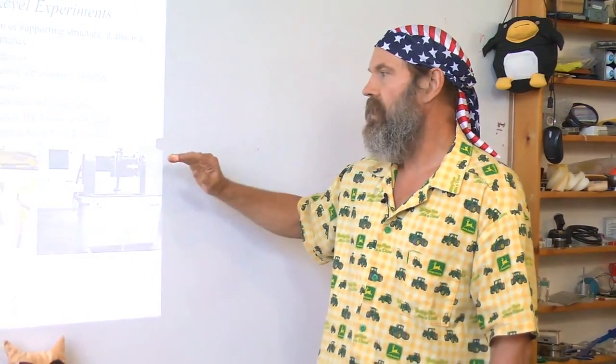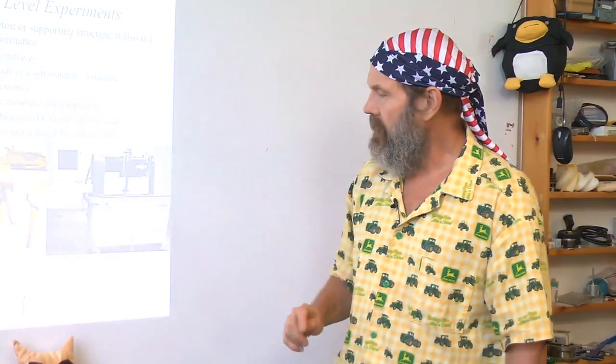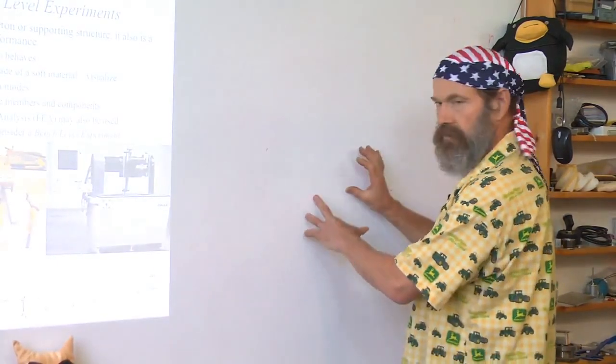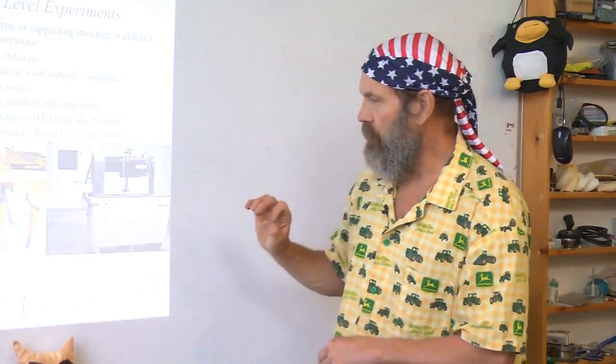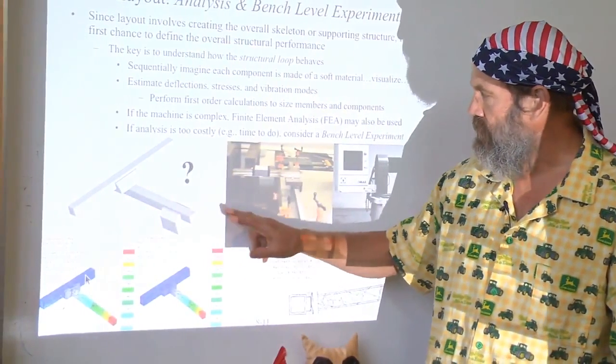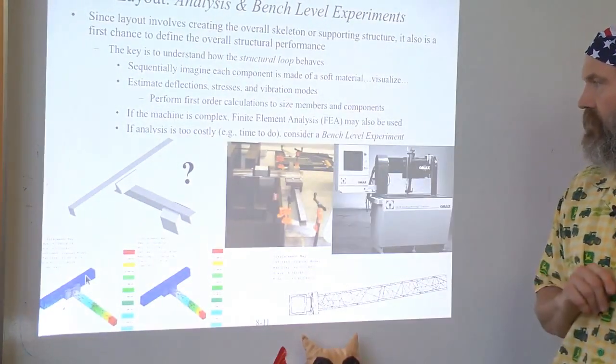A key thing is it's got to be low cost. So one of the topics we looked at was, how can we integrate the function of the bearing and the structure? And it went from some first order sketches, just like we did here, to some solid models and finite element analysis to look and see, could we use the bearing rail itself as the structure